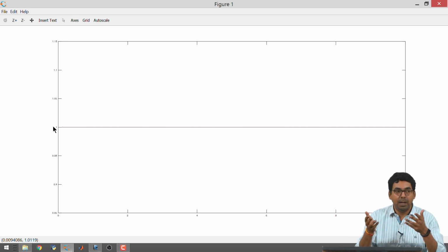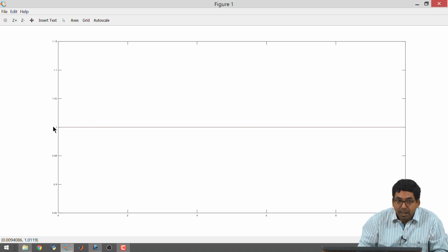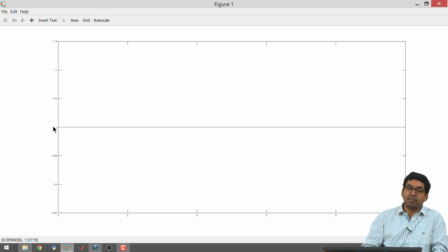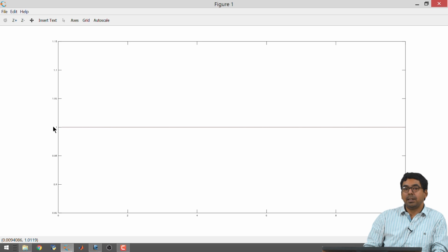Similarly, for the magnetic field, you can use the curl equation, find the magnetic field, and if you plug in M equal to 0 there, you will have no component of magnetic field along the longitudinal direction. The electric field and magnetic field will be transversal, perpendicular to each other and perpendicular to the direction of travel. This means that M equal to 0 corresponds to a plane wave or a TEM wave, the case that we are already familiar with.